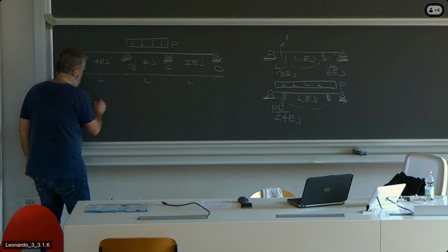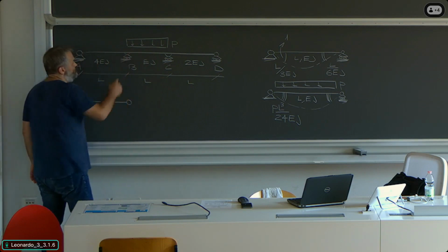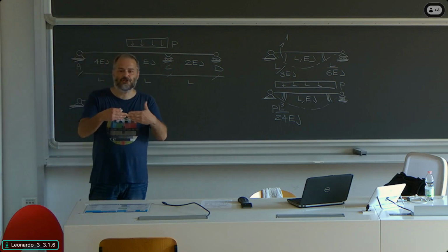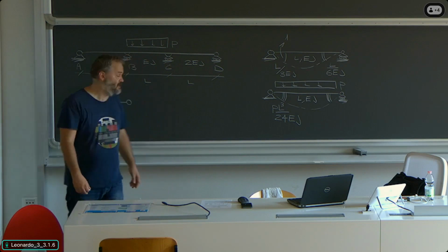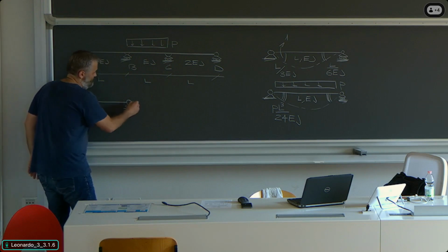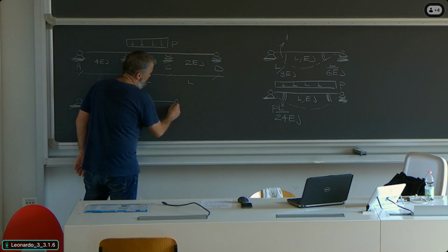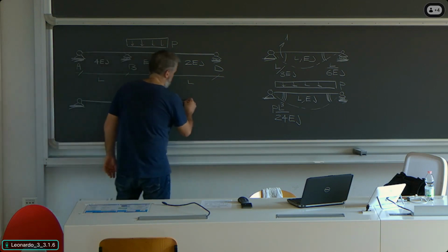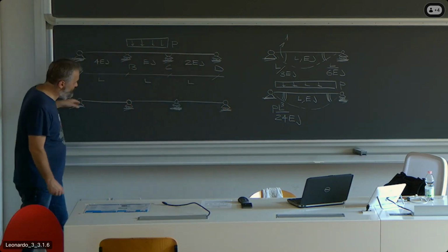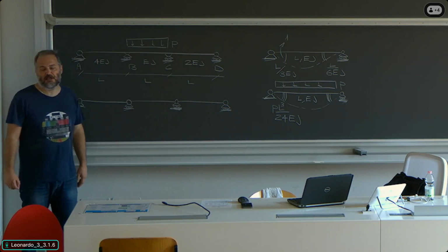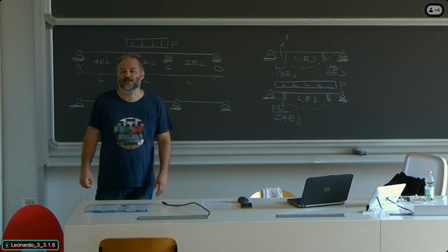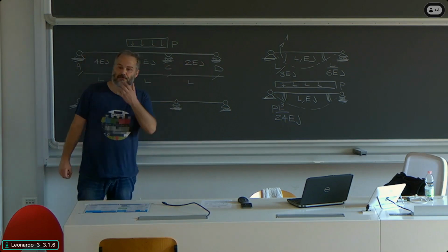As we usually do with continuous beams, we are transforming these half hinges, which imply a rotation continuity between the two adjacent spans, into full hinges like this, at point B and at point C. By doing this, our structure becomes a chain of simply supported beams. All of them are statically determinate. We can work out everything by means of standard coefficients and equilibrium equations.